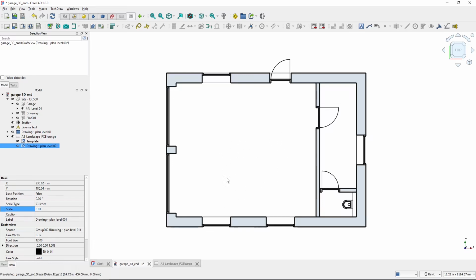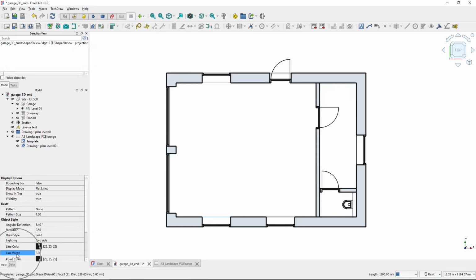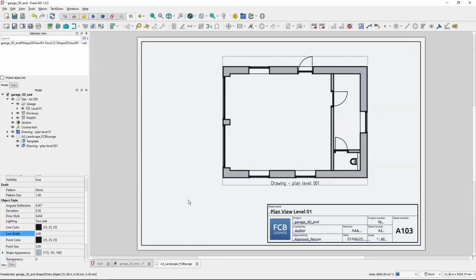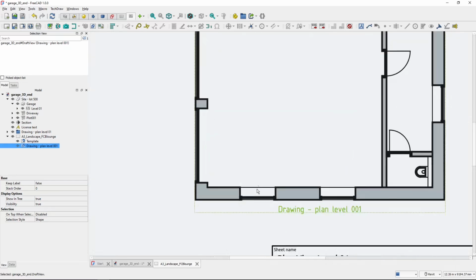Now, before creating other objects, let me show you how the line width is set up, because here we are setting the line width to 2, and this is a unitless number. This was 2, and the cut lines, if you remember, we set them to 4. But if we are working on a page, now we are working with millimeters, and you can see that the lines are in fact thicker and thinner. But what are the true widths of the lines?